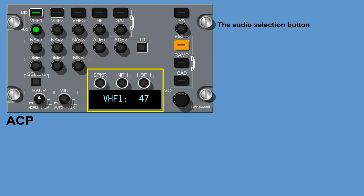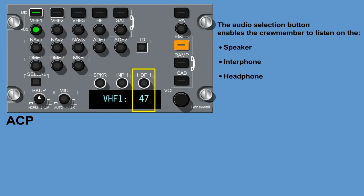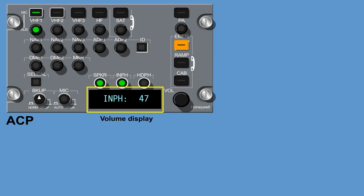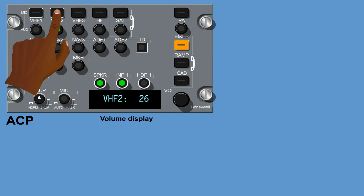The audio selection buttons enable the crew members to listen on the speaker, interphone, or headphone. A light illuminates inside the button to indicate that it is pressed. More than one selection is possible. The volume control knob allows adjustment of the most recently selected audio. The volume display shows a 4-character code and a number between 0 and 100, denoting the volume of the last active microphone audio channel or the newly selected audio channel for 15 seconds.